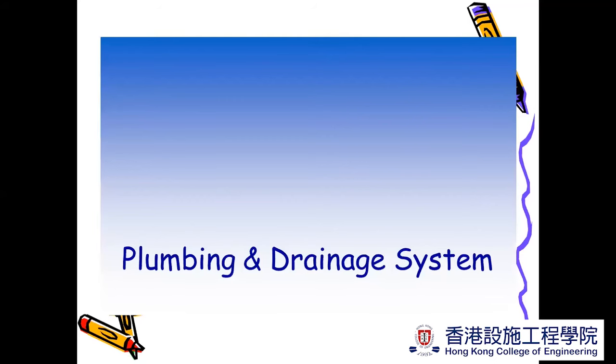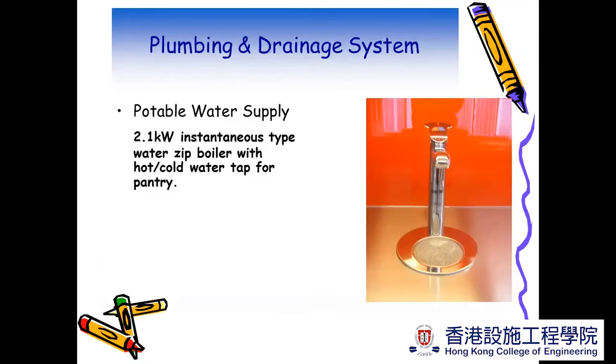Plumbing and drainage system. In this case, because it's an office area with not a lot of people, we shall use a 2.1 kilowatt instantaneous type electric water heater.